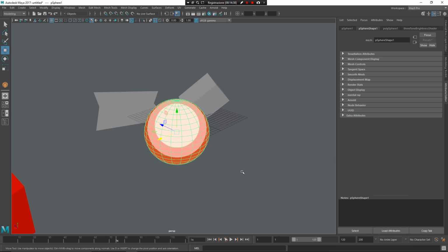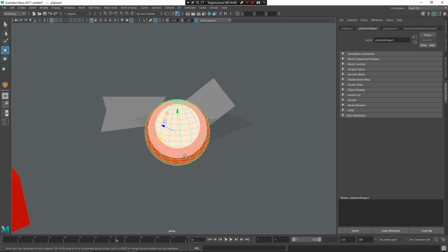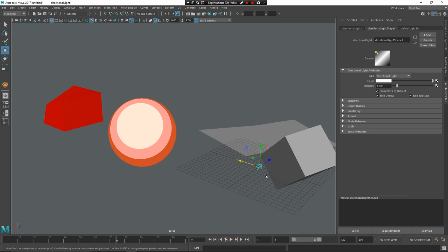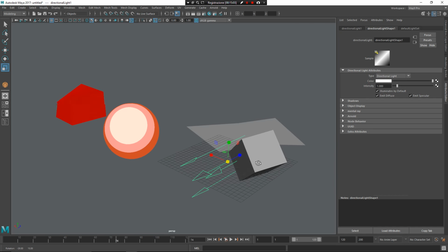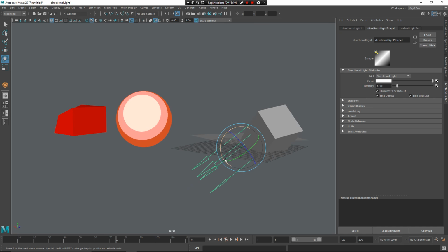But there is a problem. As you can see, actually there is only one point of light from the camera. Now I want a new light to show my cartoon shader. So look at this. I press Z again. I will use the middle mouse button. Now lights, directional light. I create a light. I want to use R to scale it and show it better, E to rotate it, and now to view the effect of this light I use a few more buttons.